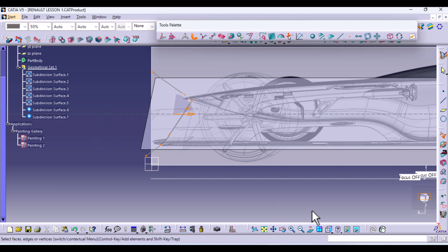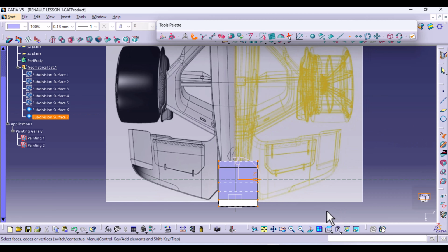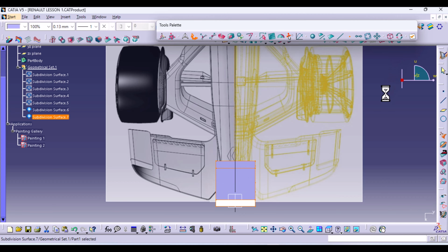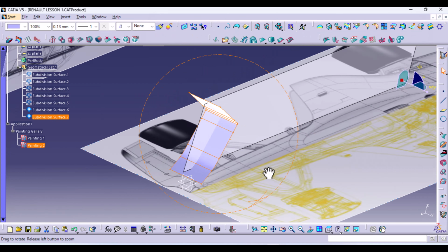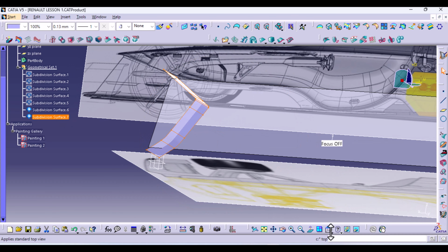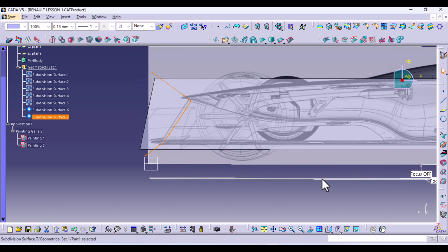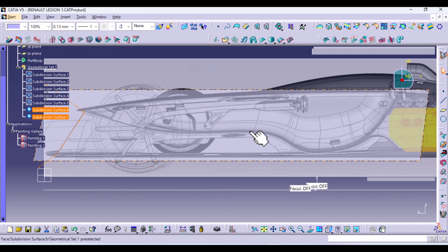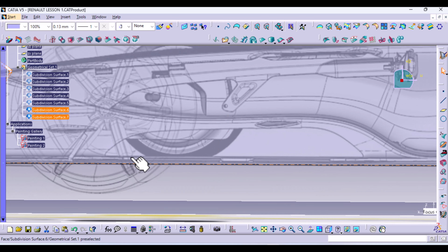We have to make sure it's covering the midsection. So go to the top view. And as long as it's cutting through the center, it's good. Exit. Okay. Then you have this bottom section here. Once again, this can be made using fillet.